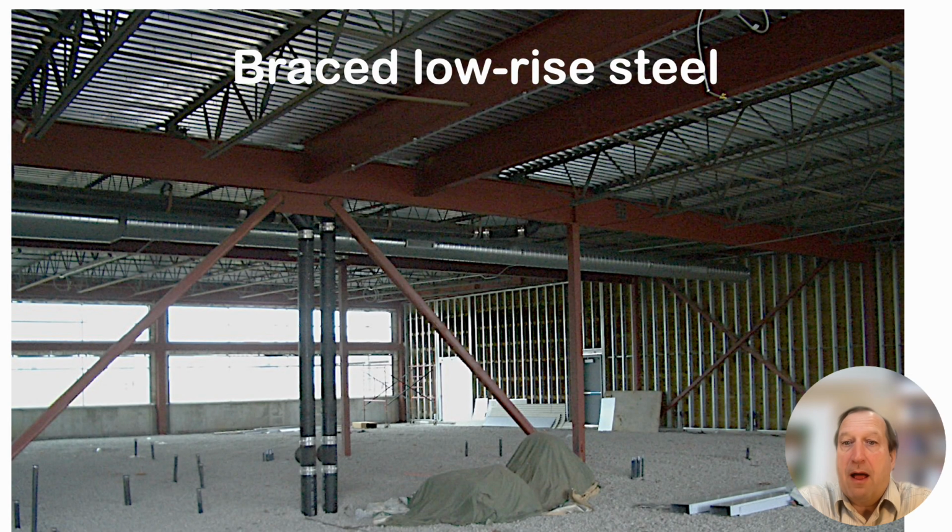So this is a photograph of what that might look like. This is a one-story strip mall under construction. You can see the red hot rolled steel and the columns and the beams, and there's pretty clear X-bracing in here to transfer lateral loads into tension and direct them direct to the foundations.